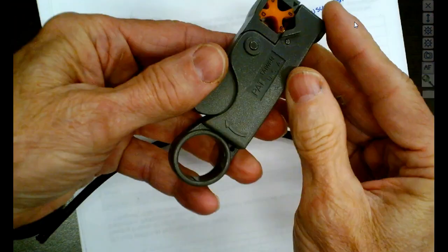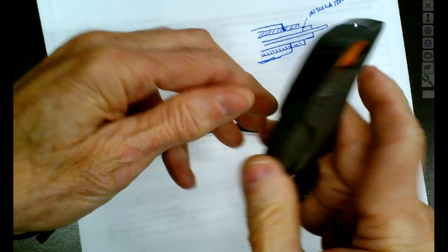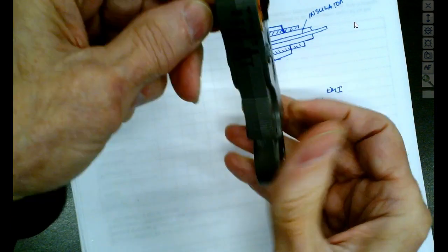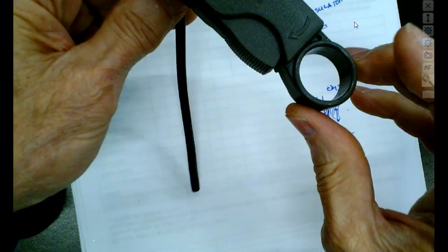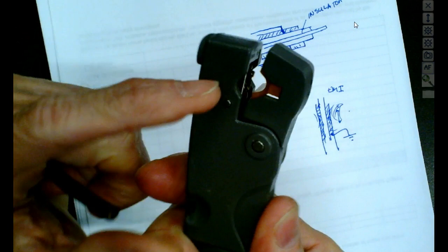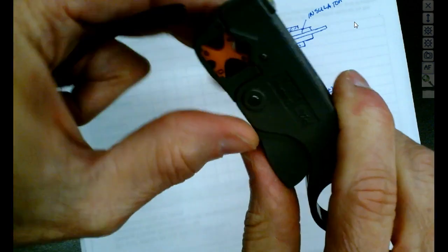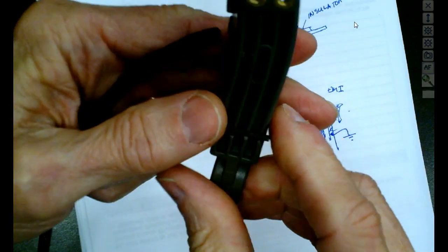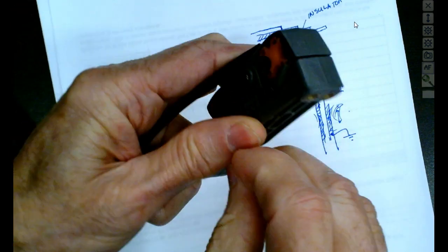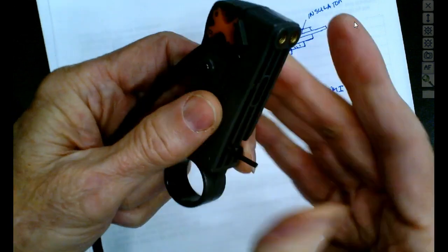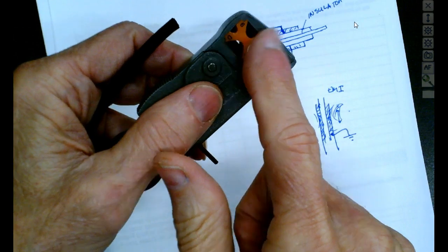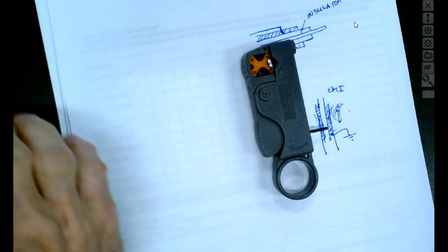And what we do is it's got a little plateau on it right here, and when I come in here I lay this in, and we line it up with the tip, and then it's got a hole back here. You can see what I'm going to do is just going to take this. Now what it has is, you can't see it, it's got blades in it, and the blades are set at different lengths. And what we have is we have an Allen wrench screw right here while we're playing around with this. So whatever cable you're going to strip, once you set it for one of them, then this slug right here should be the same.